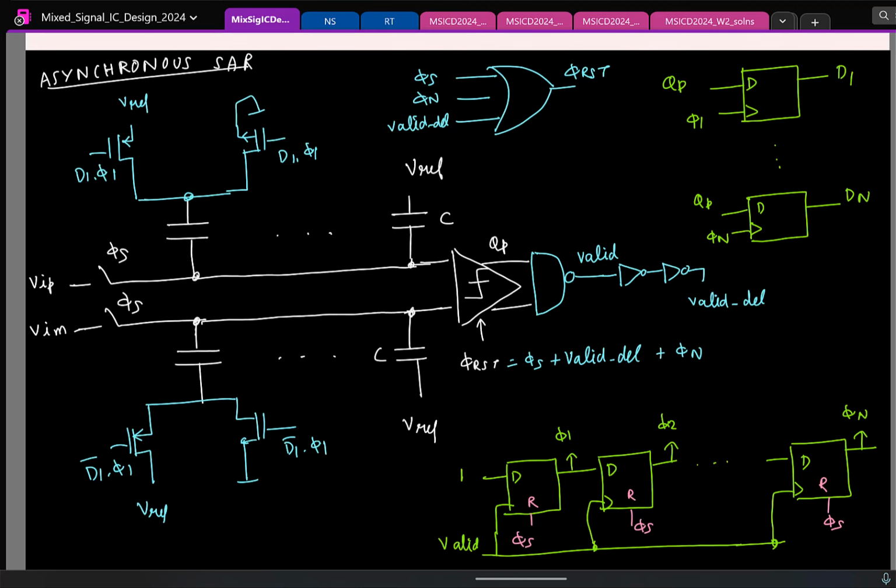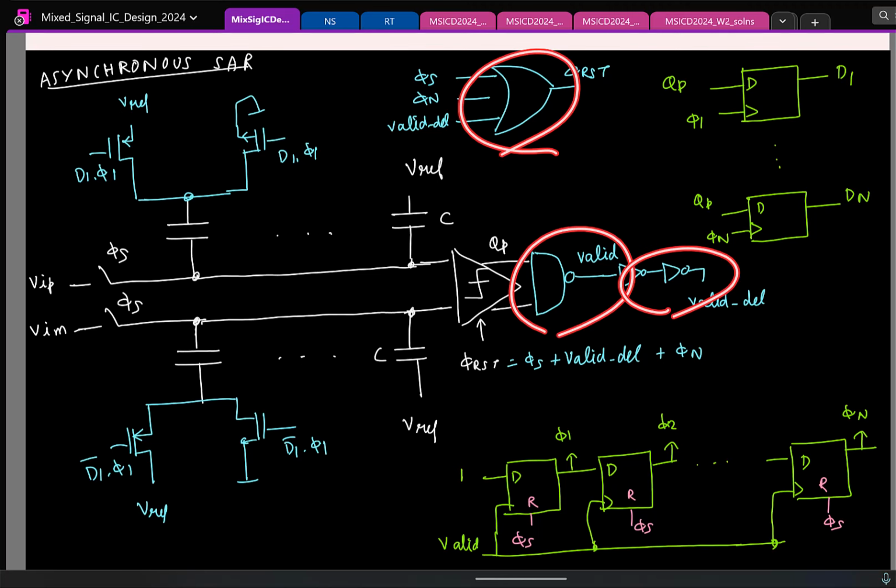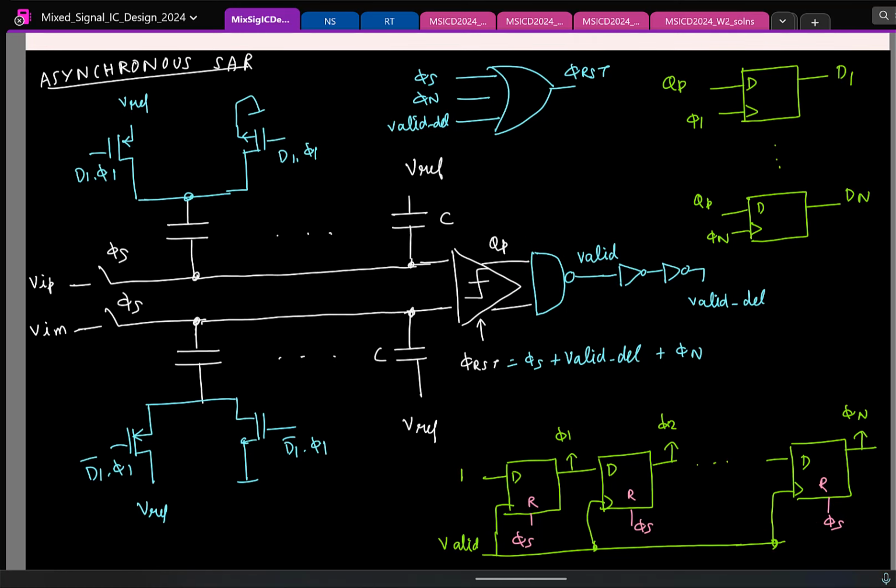Cool. So one nice thing here is, if you look at everything that I have drawn in color, blue and green, it's a NAND gate, inverters, OR gate, a bunch of flip-flops, and even these switches, right? You see I have a PMOS and NMOS. PMOS is connected to VDD, NMOS to ground. Gates of them are connected, drains are connected. So again, it should click a bulb. If you feel like it's a classic circuit, you have seen it somewhere. What is this? It's a CMOS inverter. This bunch of switches is also a CMOS inverter.